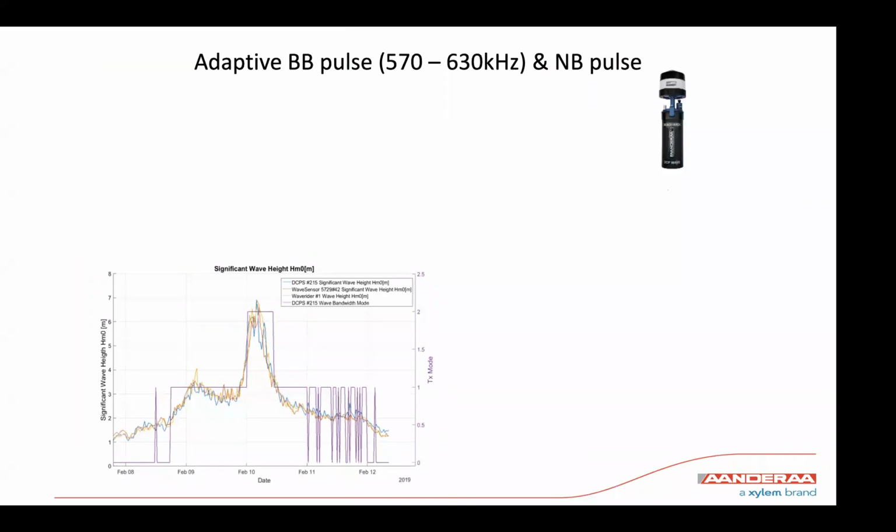So now we move to the acoustic way of measuring directional waves. And here at Aanderaa we have adapted our own technique, which we think works well. We have seen that from a 1 year test deployment, and basically what we do here is that we collect wave data acoustically. We try to go as close to the surface as possible, and to go close to the surface we use a pressure sensor on the instrument. It's not only a pressure sensor, it's a wave and tide sensor.